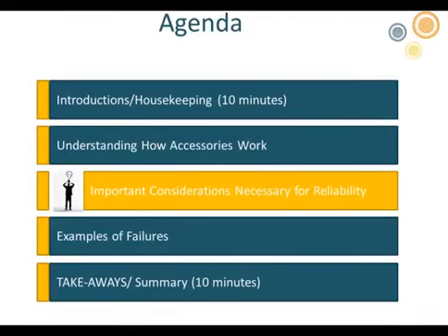It can withstand higher temperatures than EPDM, but EPDM rubber can easily withstand any of the temperatures that you see in a cable, either operating temperature or emergency overload temperature that you can see at 130 or 140 C. None of those temperatures will affect either EPDM or silicone rubber. So they're both adequate in terms of that.